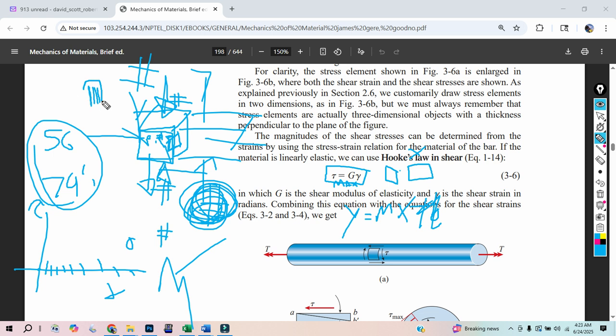But then when you tape them or glue them onto the surface of the metal, and things happen, they're going to be crisscrossed, or just have 45-degree angles, like this. You get a little rosette. If I'm pulling this way and this way, these are going to lengthen. Poisson's ratio says that the area is going to neck down and get smaller. Electrical resistance goes up, and we can measure that to a high degree. But literally, if I just hand you a chunk of steel and I say 2 millimeters, that ain't helpful.